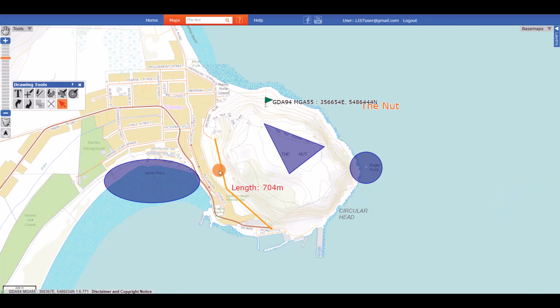Notice that when you select a line, orange circles appear where the line changes direction. These points are called nodes. You can move the individual nodes by clicking and dragging them. You can also add new nodes by clicking and dragging the transparent nodes that show at the midpoints of existing line segments. To remove unwanted nodes, hover your mouse cursor over a node so that the cursor icon changes to a four-way arrow, and then press the Delete key on your keyboard.